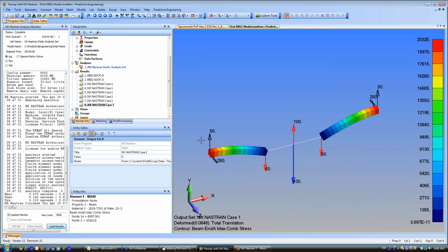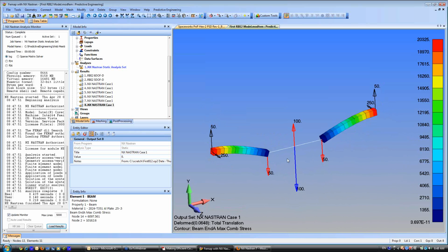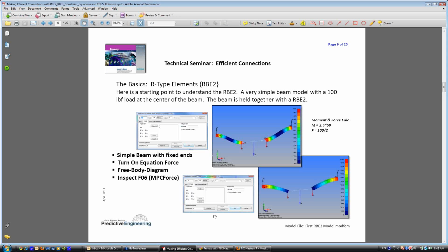And it's nice. I like having the free body diagram on to do these sort of basic mechanics. So now you're at 50 pounds, 5 units, 250. You see how the numbers change there? Hey, basic, direct. I think most everybody feels pretty comfortable using RBE2s. It's rigid. Everything connects up pretty clean.